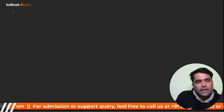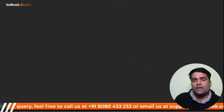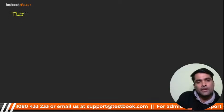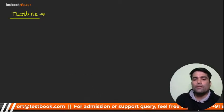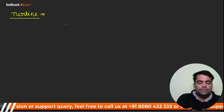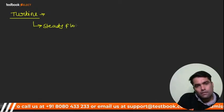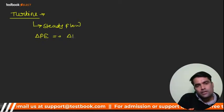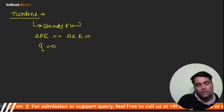Now, when we apply this equation to the turbine, जब हमने टरबाइन पे लगाया ये इक्वेशन, so what did we get at that time? My dear, see here, in the turbine the assumption will be steady flow. And the change in potential energy and kinetic energy is 0. And it is adiabatic, that is Q is equal to 0, right?